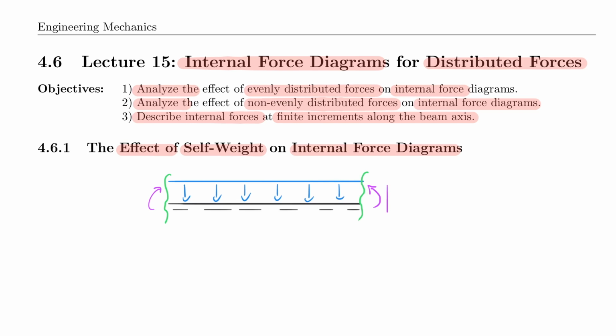I have the shear forces on both sides because I cut on both sides. And I also would have normal forces on both sides, which I am not trying to calculate right now, but I want to think about how they conceptually would look like. And to conceptualize that, I want to introduce a length here of that member that could be really anything. It could be as short as dx, it could be 5 meters or 5 feet or whatever, but I just make this x and maybe meter long.